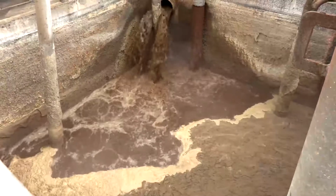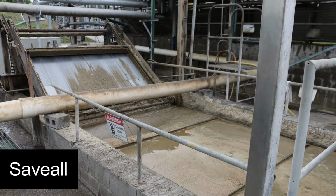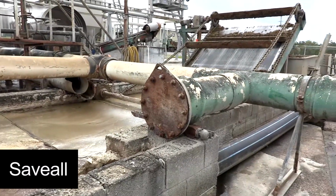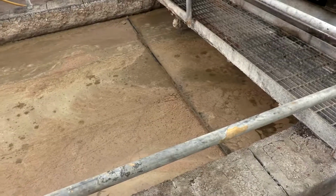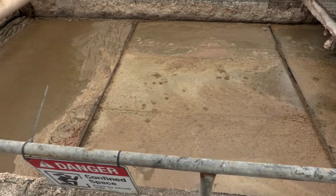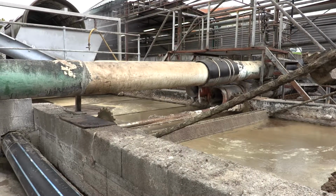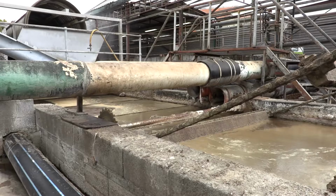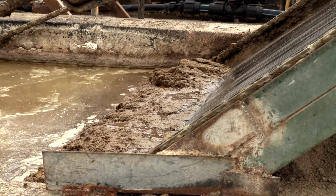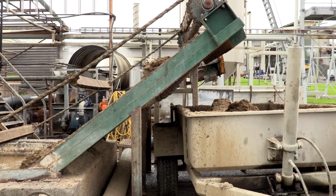Technologies used for reducing oils and grease include a save-all, which is simply a large settling tank in which the raw wastewater enters, generally after pre-screening. Sufficient time, usually 30 minutes, allows fats to separate and float to the top, and for heavier solids to sink to the tank base. Surface scrapers gently tease the floating fat off the liquid surface for discharge in a skip or to a screw press for reprocessing. Some save-alls are also fitted with base scrapers to remove solids in a similar manner.